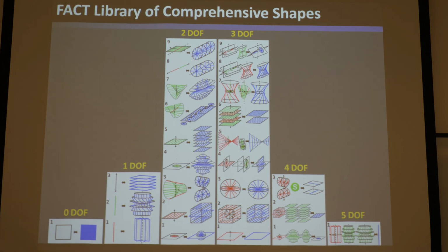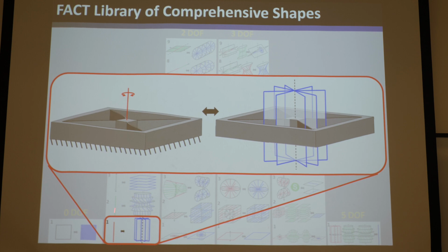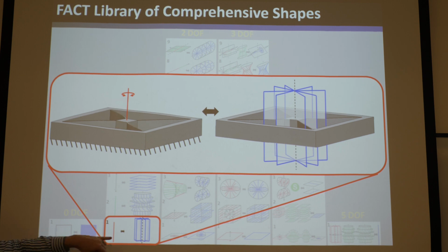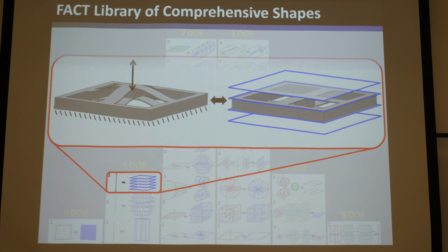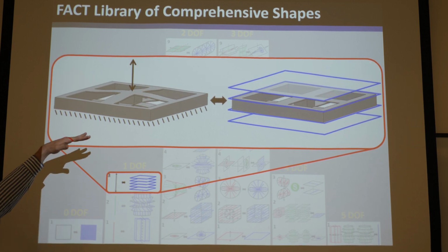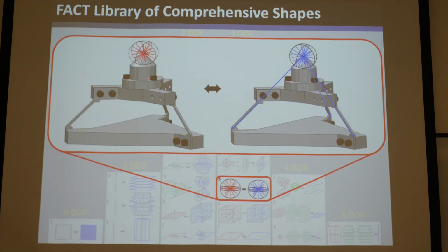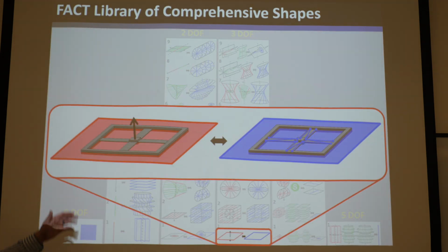Okay, and the way it works is, if you have a system that rotates, the reason is because its flexible elements all lie on intersecting planes of its constraint space, right? And the reason this works with the translation is because its blades lie on parallel stacked planes of its constraint space. And the reason this guy works is because its wires are within this guy's constraint space. And the reason this works is because these 4 blades were redundantly constrained within that guy's constraint space.